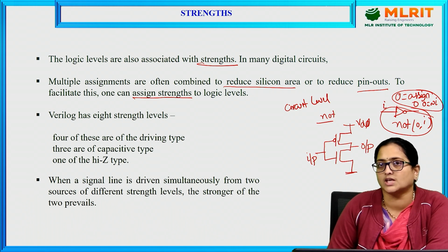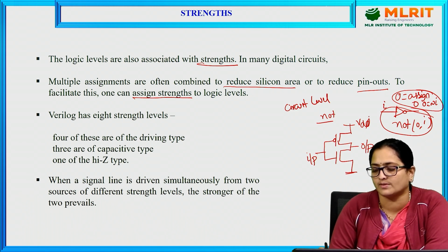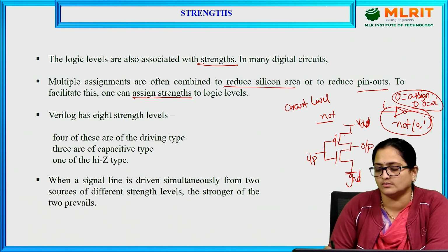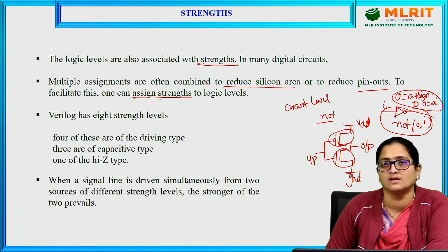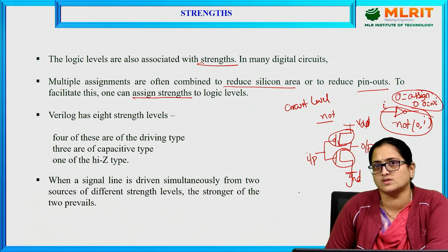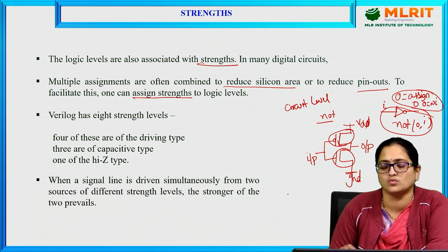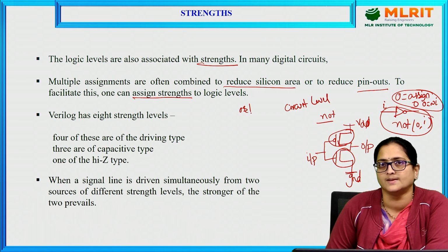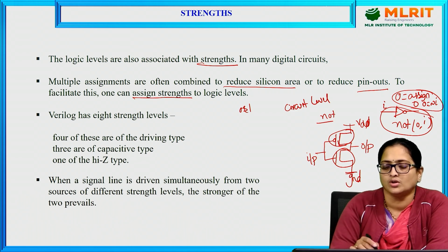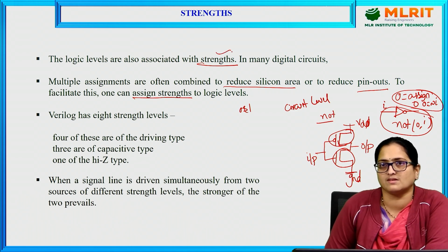But here in circuit level designing, when you want to represent the VDD or the ground, or you want to represent the flow of this transistor switching on and off, levels can be represented by using these strengths. It's not possible to always use zeros and ones to represent the logic level. We may also use these strengths to represent the flow of the power signals.